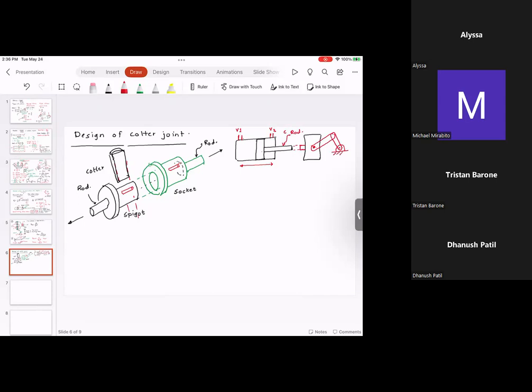So what you have is the steam engine. Now you want some easy way to separate out the crosshead from the engine. So this is the crosshead, and the crosshead slides back and forth. The steam engine typically is stationary. So you are going to convert the reciprocating motion of the piston into a circular motion of the crankshaft.